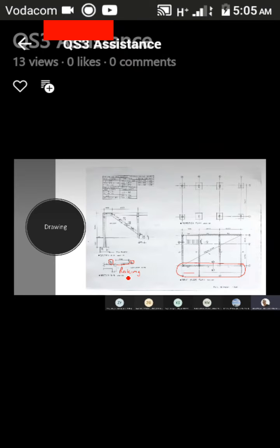Now, I have illustrated that in my first column of my description. So it will be the thickness of 0.13, and I will then have a formwork to raking soffits of slabs, including propping up, exceeding 1.5 and not exceeding 3.5 meters high from bearing level.